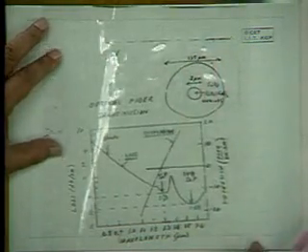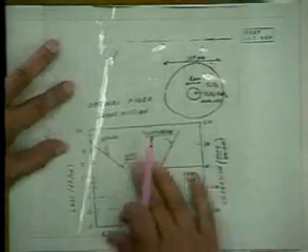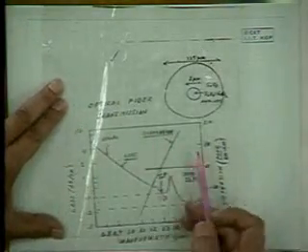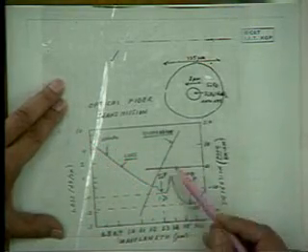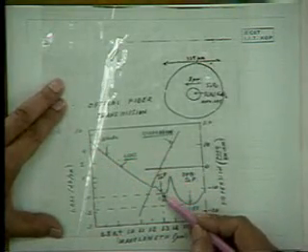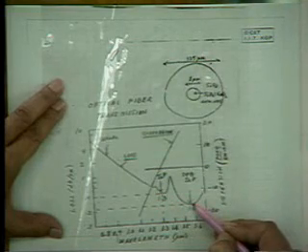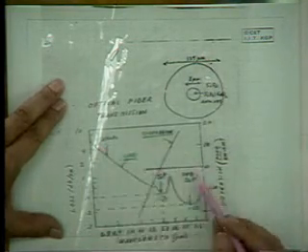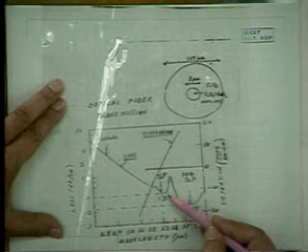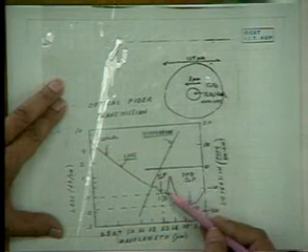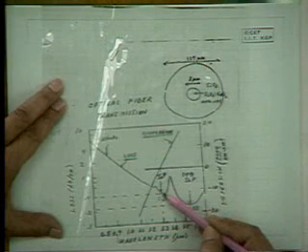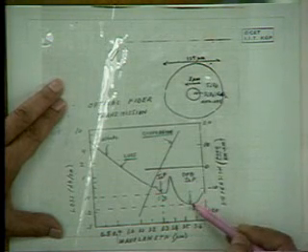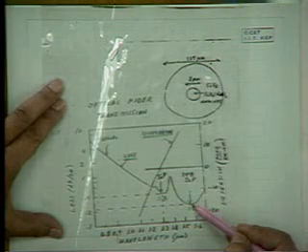And if we look at the loss versus wavelength, we find that the loss is a minimum at 1.3 and 1.55 microns. So obviously, if you want to send light long distances, we would like the sources and the detectors to operate at 1.3 microns and 1.55 microns.